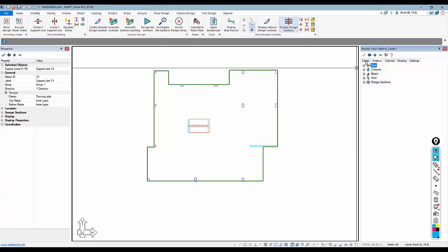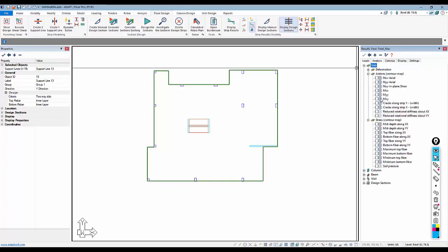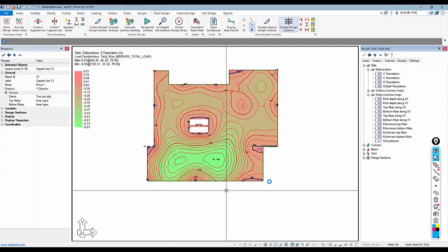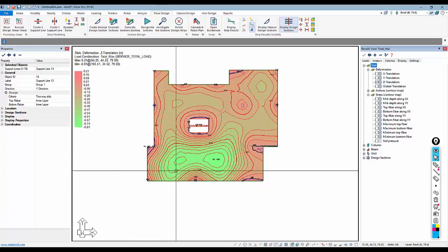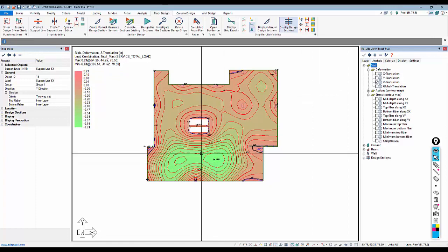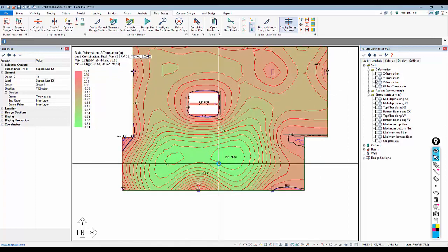If we go, for example, to the skip max and min, let's go ahead and collapse that. I'll collapse this also. We're going to go to the service combination here. We have this one called total max, and if we go ahead and produce the deflection result for total max, this just indicates an envelope of all patterns based on that maximum value. Maximum meaning maximum vertical deflection downward.